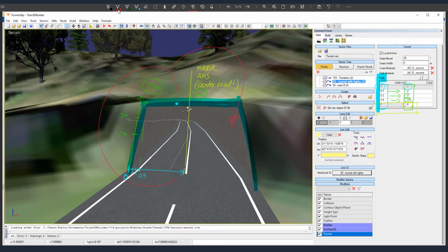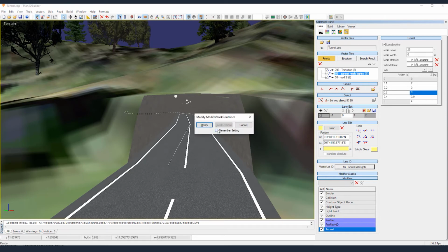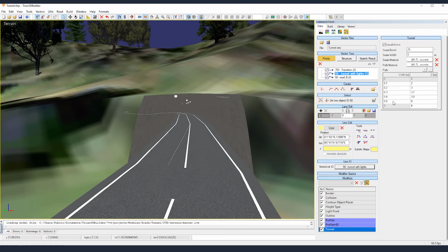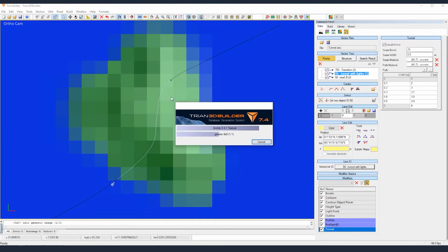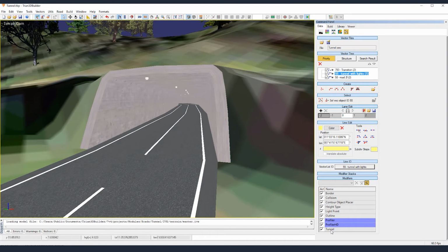Let's see how it is in practice. I'm gonna try to make that profile a bit smoother, like make a rounded corner on the top, and I can imagine that to do that I should add some points and the distance on C a bit smaller between those points, like the final points that will be at that corner. Don't forget to bring back the seam width, and let's generate it. So yeah, that's smoother. So we are done with the tunnel modifier.